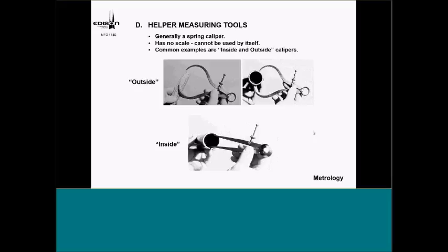Now, when we talk about scale and these calipers, one of the first parts that they measure, this is what they have to use. They have to use inside, outside calipers and a 6-inch rule. I want them to start understanding, first of all, how to measure with the calipers and get the proper feel. In other words, you don't force the spring. But how do you transpose the measurement? So we really start getting into doing some measurement.